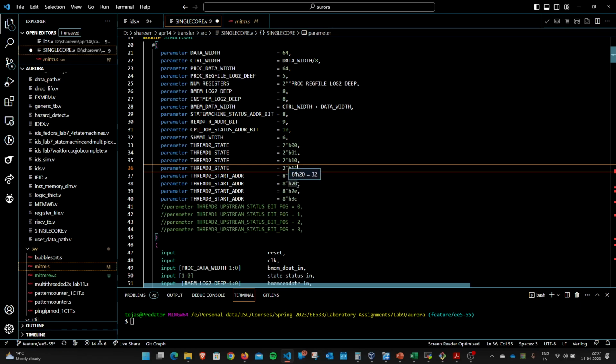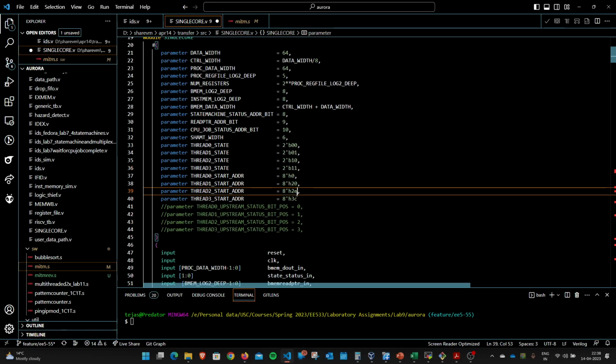Depending on our assembly language, when we generate the binaries from the compiler, which we feed to the COE file and which gets coupled with our IP core of the data instruction memory, we need to give the addresses so that every thread knows which instruction it has to execute.